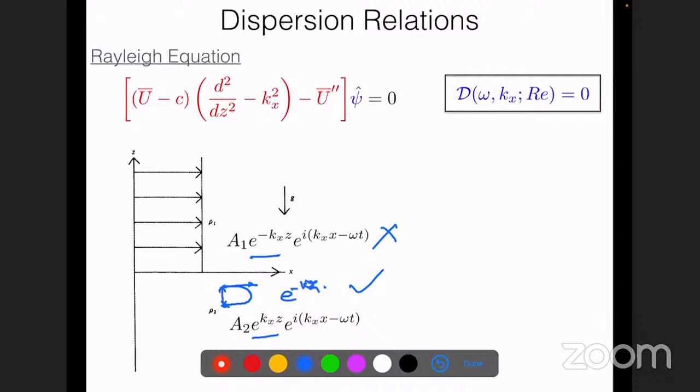So over this small region that you make, the loop that you make, when you have gone from the same x location and come back to that same x location, but with a certain vertical displacement, the fluid velocity has reversed and it is taking you backward. When it is going in the backward direction, you are at a slightly deeper location. At that deeper location, the background flow is weaker. It is not able to transport you as much as you were transported in the forward direction. Your transport in the forward direction was happening at a location closer to the interface than your transport in the backward direction when you are in a slightly deeper location. So this mismatch in the two transports, where you have a slightly larger transport going forward than going backward, leads you to a drift.